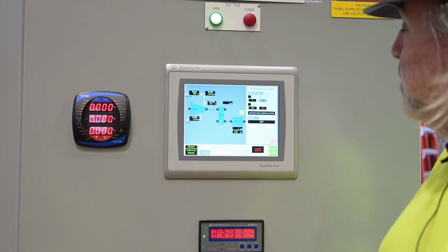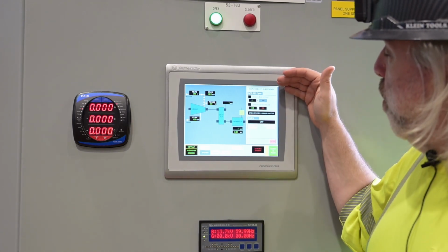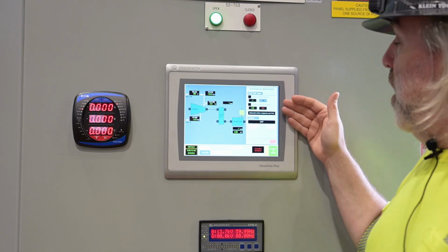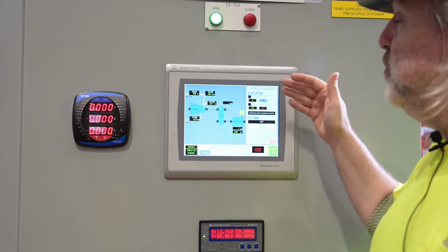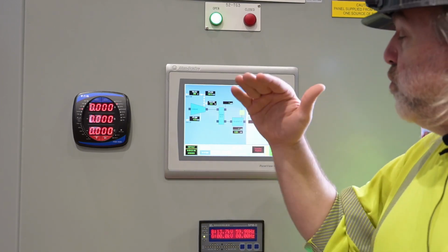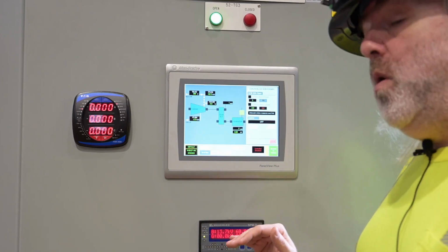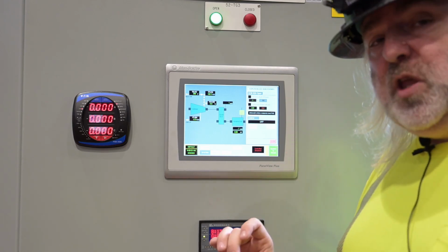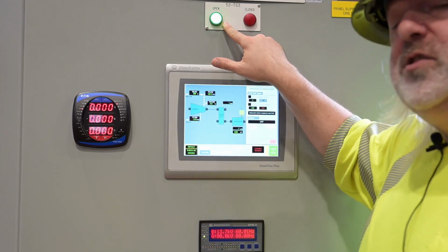Stop. Once you press the stop button, you bring up the controlled shutdown screen. A controlled shutdown will do two different things. If the breaker is open, the controlled shutdown will ramp the speed set point to 0. Once the speed set point achieves 0 RPM, it'll then trip the unit. That is when the breaker is open.